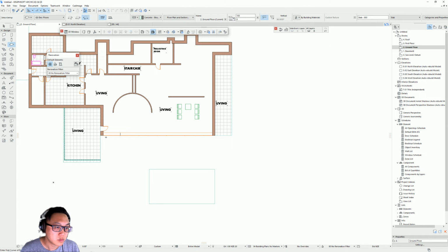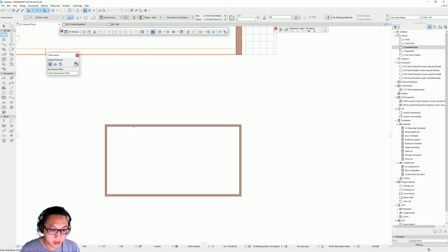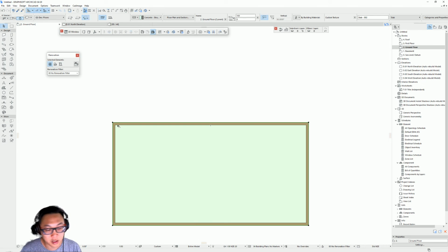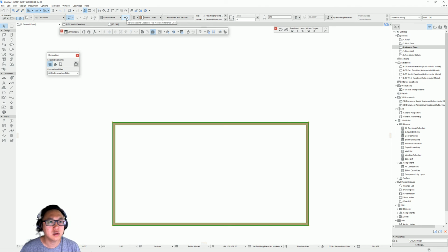and then walls, wall tool here, you can set up the sizing. You can either click on each corner to make your walls, or you can use the magic wand. Select the wall tool, press spacebar, click within the space of the slab, and then you have your walls. And if they're not in the correct position, like if there's outside, right now they're correct, so you don't need to do anything. But if you wanted to, you can select the walls and change the, what is it called, reference line, just to put them outside or inside.